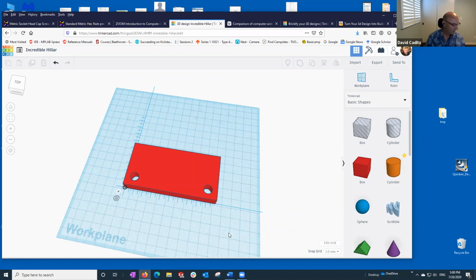And we talked about rulers just now, which are really useful for placing objects. We talked about work planes, which are really useful for stacking objects on top of each other, temporary work planes. The concept of turning something into a hole before you merge it, that's really important. And the basic concept of how you create things, which is you start from primitive shapes and build it into some kind of shape that you want.